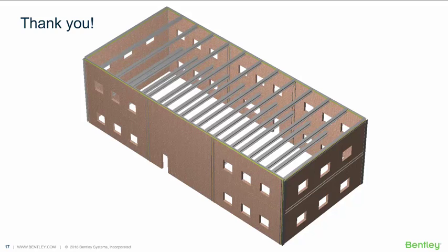Okay, Francisco, I'm not sure if you got this one or not, but for solid walls, there is not a good method to model boundary elements with column reinforcing at the ends and minimum reinforcing at the center for concrete shear walls. So right, RAM Concrete is a little weak in that sense.